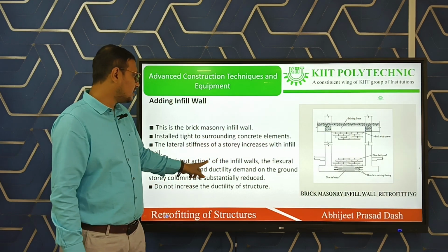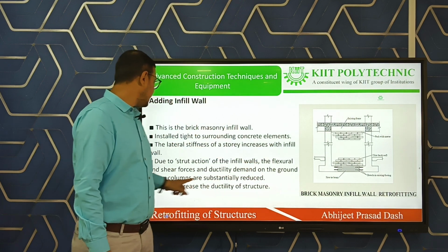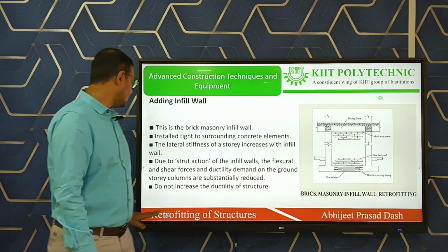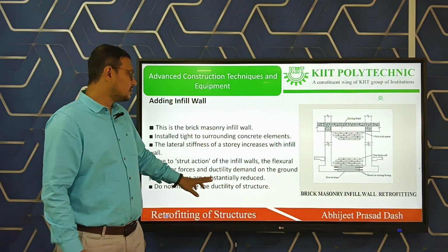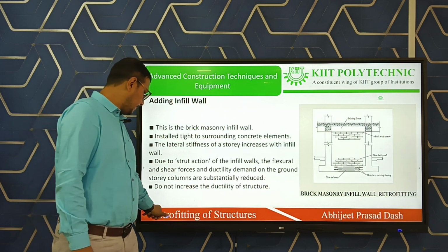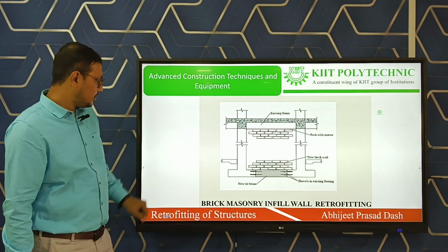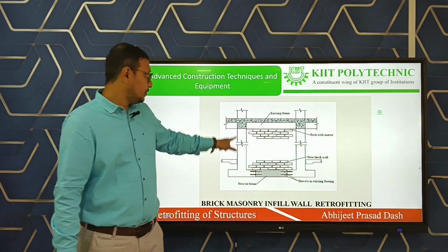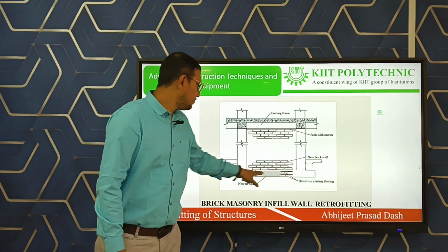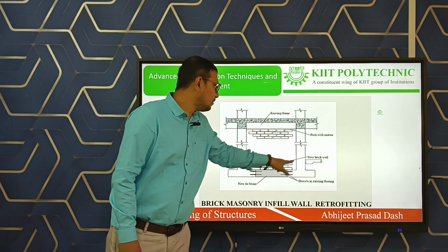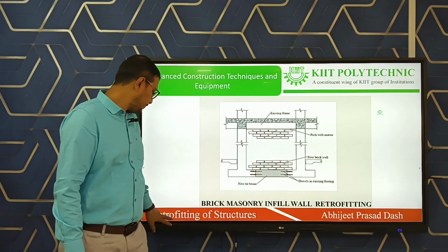Due to strut action of the infill walls, the flexural and shear forces and ductility demand on the ground story columns are substantially reduced. So this is your brick masonry infill wall retrofitting. This is the existing frame structure and we are providing the new brick infill wall.